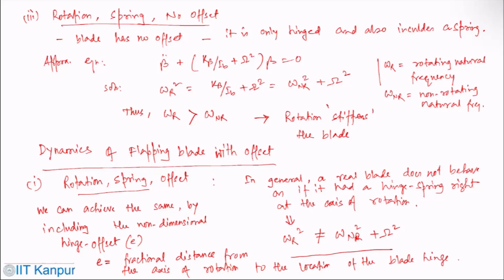So now we can actually estimate all the constants of the hinge spring model once we know the natural frequencies of the rotating and non-rotating real blade.